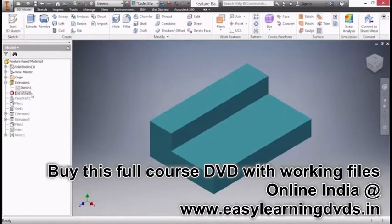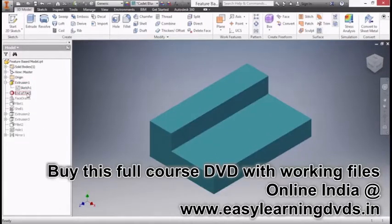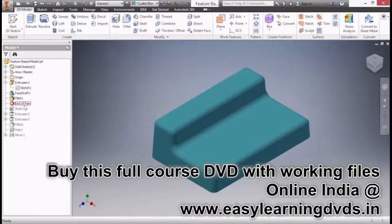So here I can see this initial sketch helped create this feature, extrusion 1. And then if I drag this below face draft, you can see a small draft was added to this part. And now I drag it below fillet 1. You can see the smooth edges were added to this. If you were doing those particular types of fillets in an archaic 2D drafting system, it'd be very tedious to do so. Here it's quite easy.